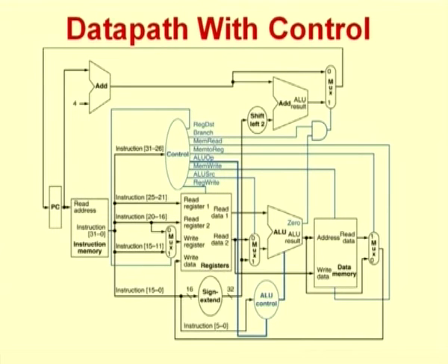So once you have derived this, now we can see how the input to the control unit will go. Okay, so if you look at this, let's see what we have. From the instruction, remember the rest of the things are the same. This piece here in the center is our new control that I have added now. How do I look at the data coming from the instruction memory? The instruction comes, which is 32-bit data, so 0 to 31. That data I take, and the most significant bits 26 to 31 give me the opcode, which goes as input to the control unit.